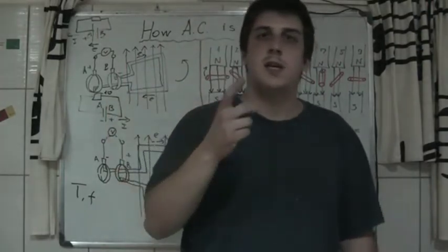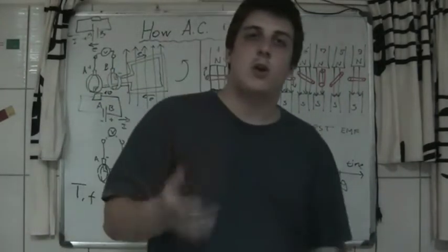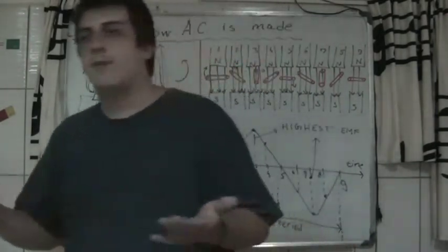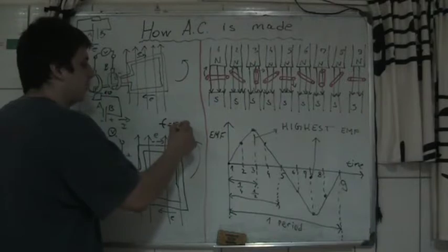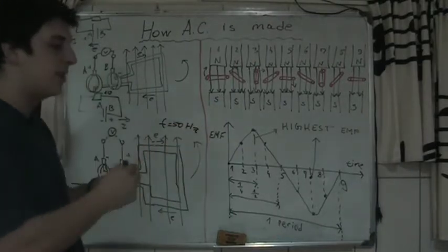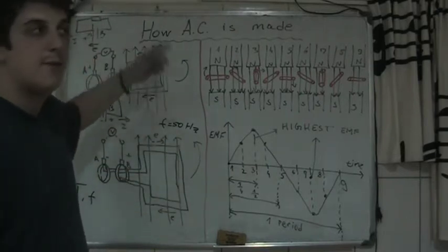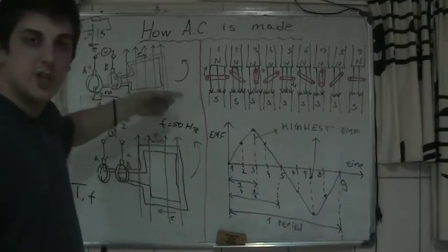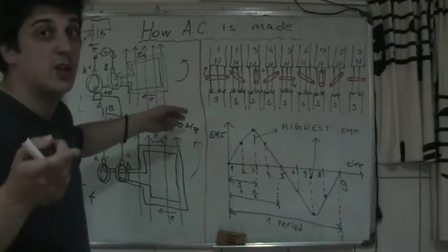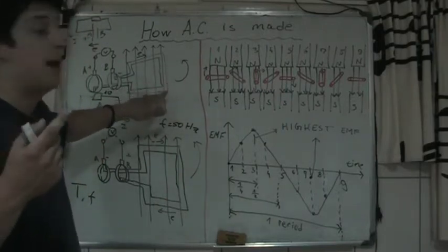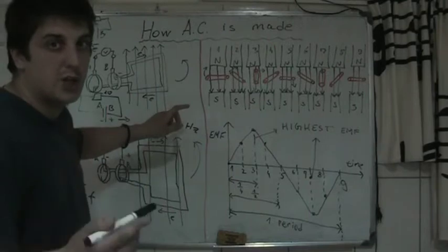And the period is one rotation, but calculated in seconds. In Europe we have a frequency of 50 Hertz. So our power plants have generators that make 50 rotations in 1 second. So in 1 minute, that is 3000 rotations per minute. And if you're in USA, all your generators make 3600 rotations in 1 minute.